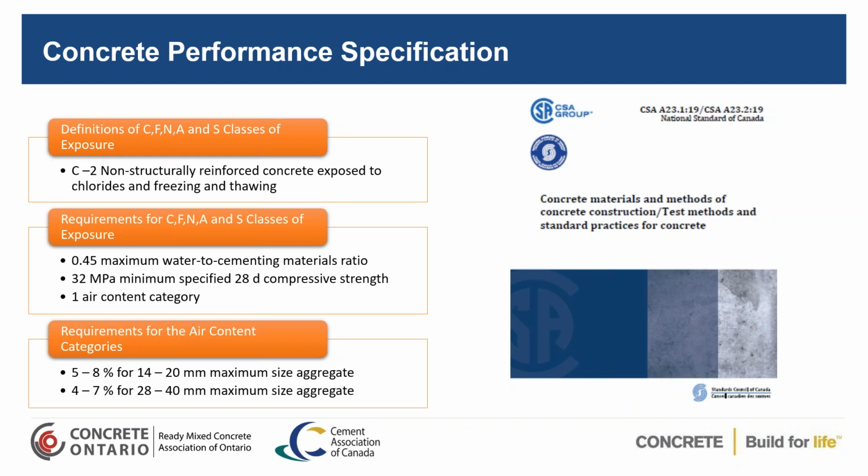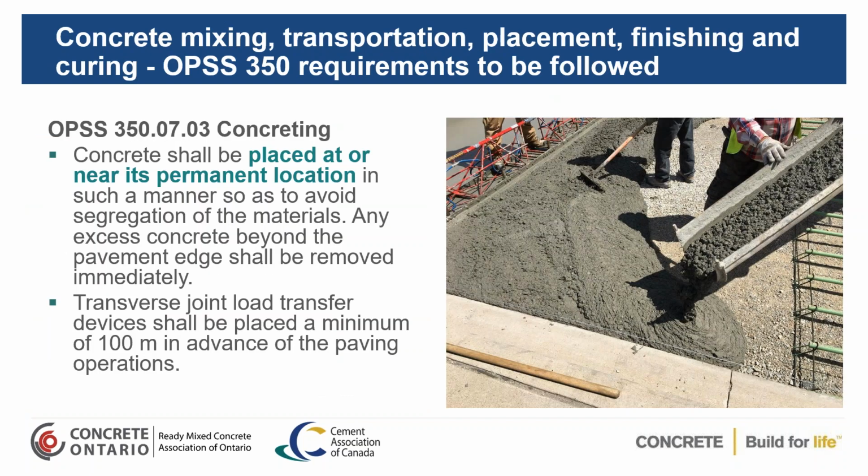And if we went into greater detail, which we don't have the time for, there's a shape factor and a spacing factor that is done through the air entraining to provide you with the most durable concrete. So it's very important to have that air entraining.